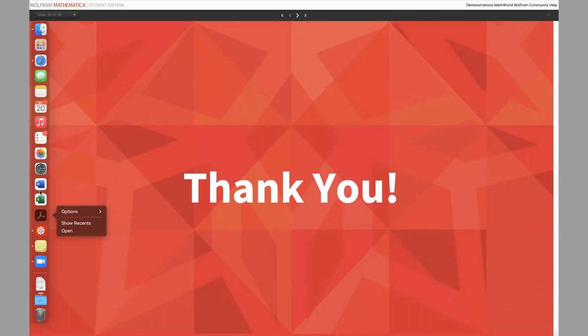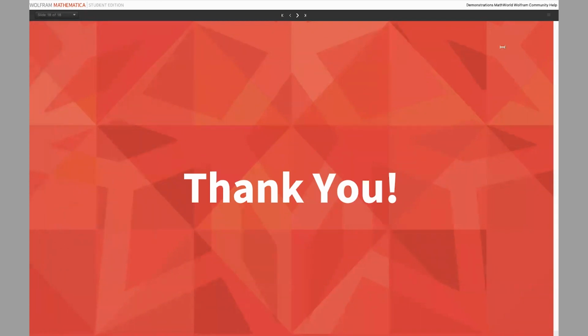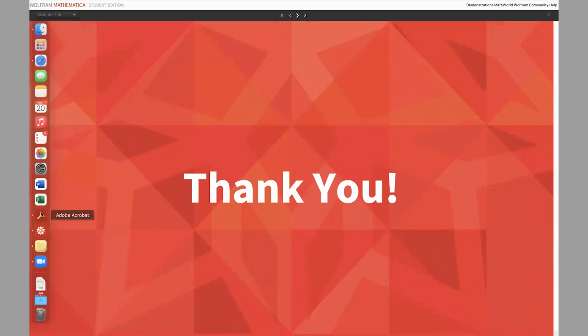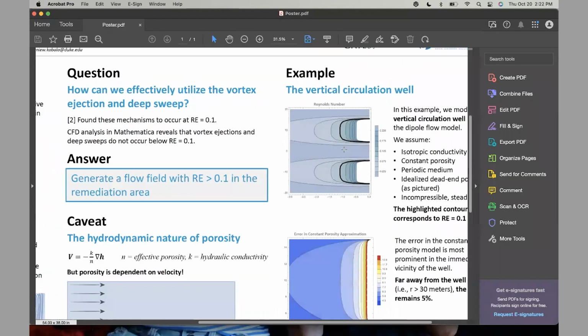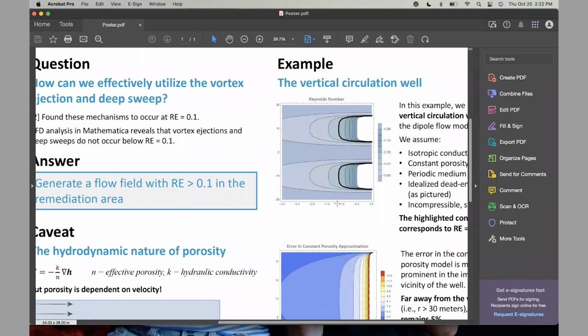But let me pull up an image of a vertical circulation well, and we can see how we would move contaminants within the groundwater matrix. So here we have a vertical circulation well. What we're doing is pumping; think about dipole flow. You have a source and a sink, and one's pumping out and one's pulling in. Up here, we have our source, and then we have our sink. As we're pushing, our water comes out of this source and gets pulled into our sink. So our contaminants are effectively moving along this dipole flow pattern, and we're capturing them right here at the well bore.